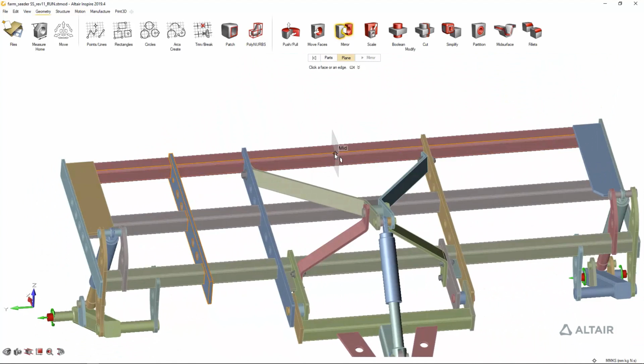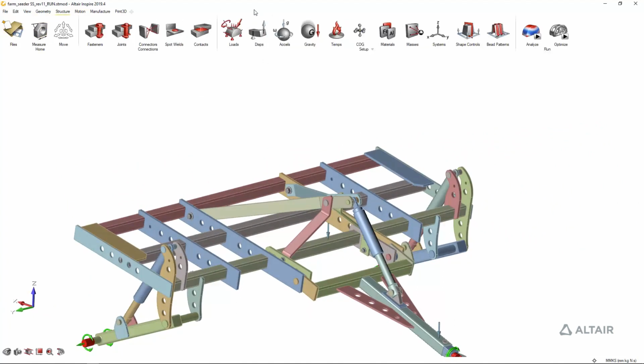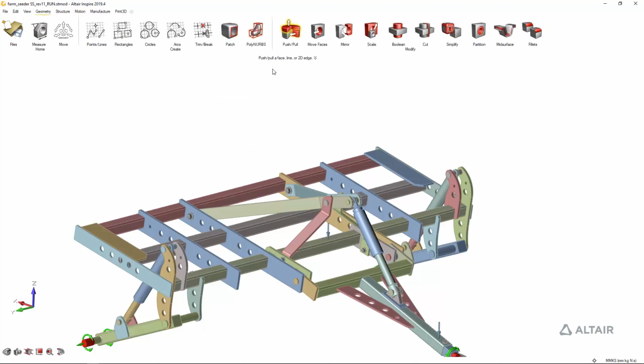It has the full geometry capabilities, so it's very powerful in quickly making changes to your design and rerunning simulation using SimSolid. Again, press F8 on your keyboard, or simply right-click in Analysis, Quick Run. That's going to again call SimSolid and rerun the new design iteration. It takes about 10-15 seconds again to get you the new results.